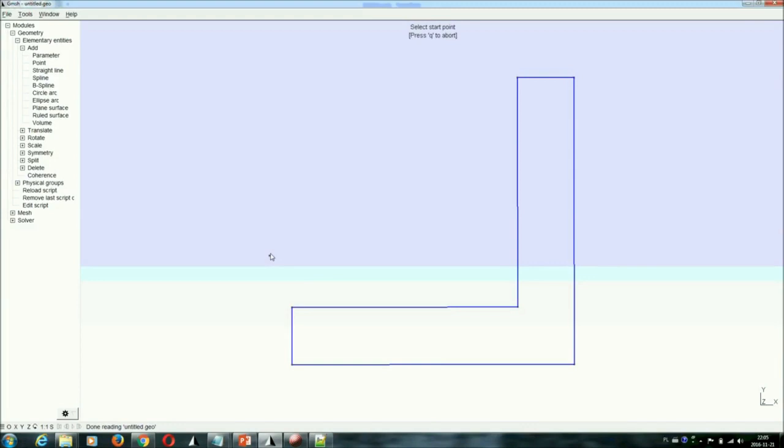Right now what we are going to do, we are going to create a mesh in this geometry, but the Gmsh philosophy is the following. We have to create a surface and define then physical domain. So it's not enough to only create lines. We are selecting plane surface, and let's simply choose surface boundary. If Gmsh is able to figure out what is the boundary of the plane surface, then it selects it automatically. Otherwise, you would need to select it manually.